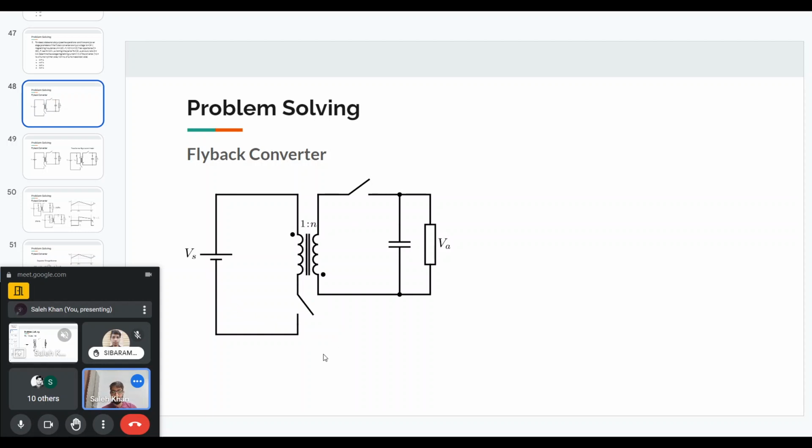So I was saying that because of this isolation, the noise is not propagated. So that is another reason why I may use isolated transformers. Another can be if we want to have an output which is not at the same ground as the input. For example, if we want to connect another circuit in series at the output, sometimes that is not possible in non-isolated converters.